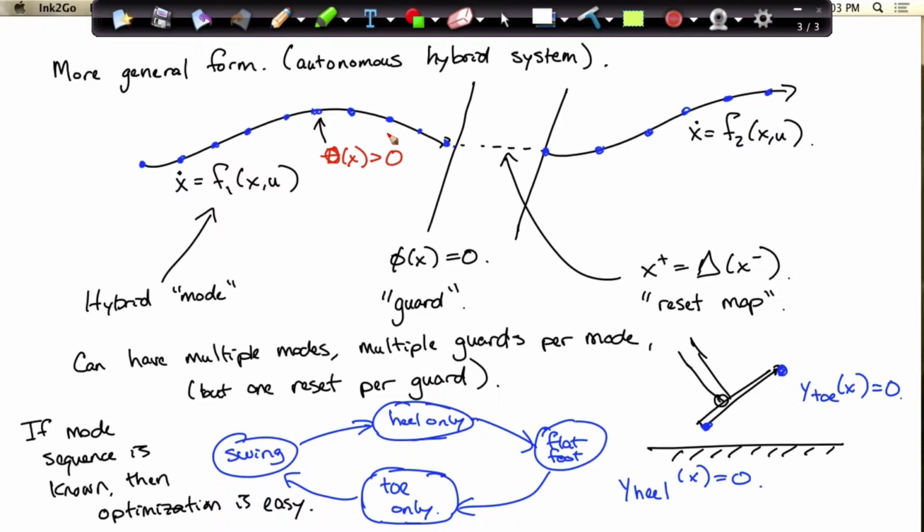But does that make sense? You could just write that down in a very general way, if you can just describe the modes of your system. In fact, if you have a rigid body system and you want to write down the reset map that takes me from this mode to another mode, and they're both given by Lagrangian mechanics, it's sort of the generalization of computing the reset map for impulsive collisions. If I know the pre-mode and the post-mode, it's actually pretty straightforward.